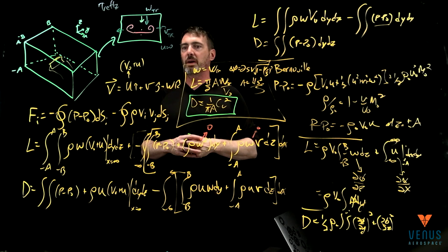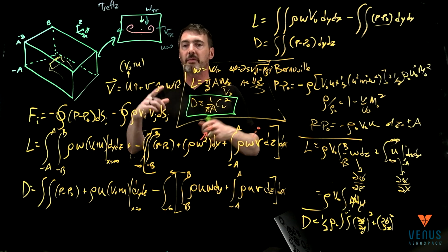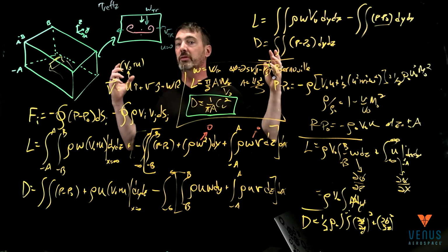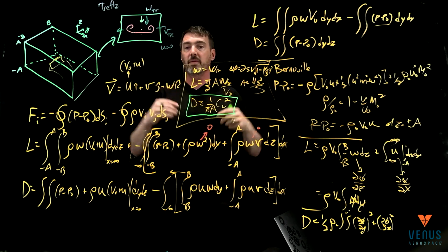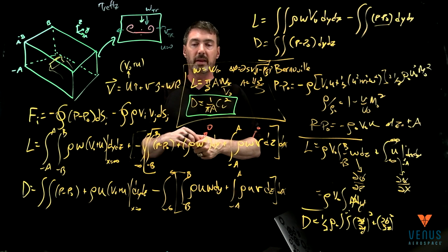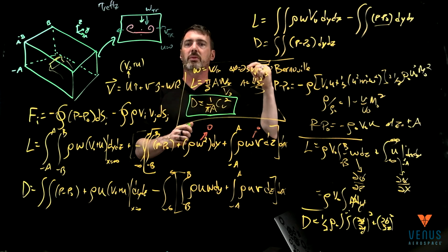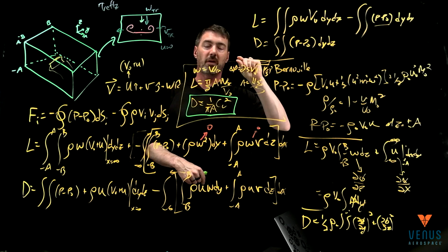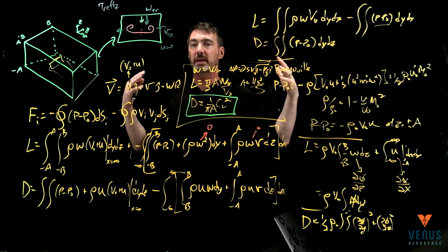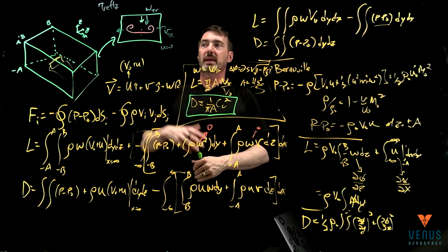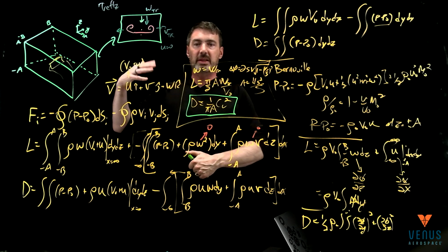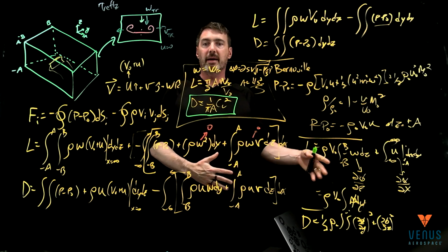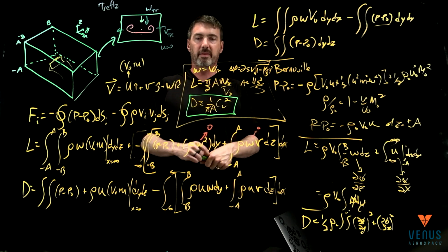You know, we've talked about the vortices that actually come off. As long as you're imposing the Kutta condition, you have to impose a vortex in order to have the velocity come off evenly off of the trailing edge. It's because of viscosity, but as long as you impose that velocity matching condition, the first order effect of viscosity is just to provide the fact that you get these vortices. And then we can work this potential theory, carry through all the math, and we end up getting this very awesome result.